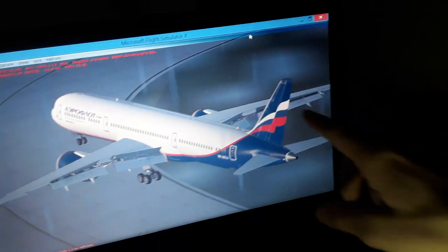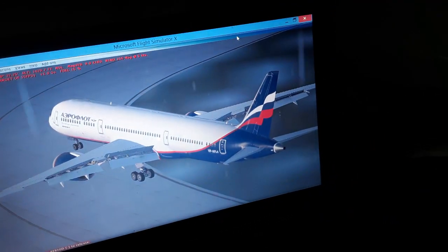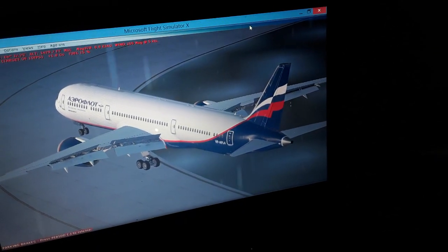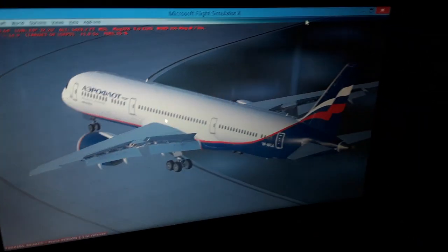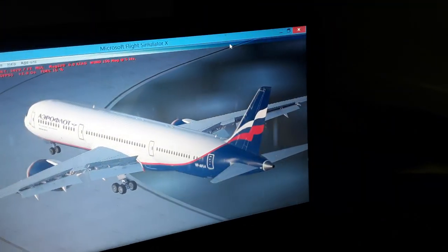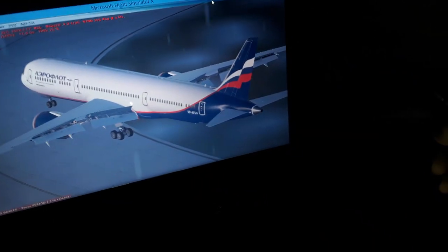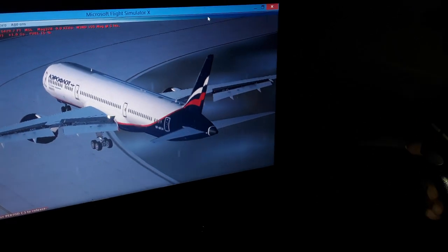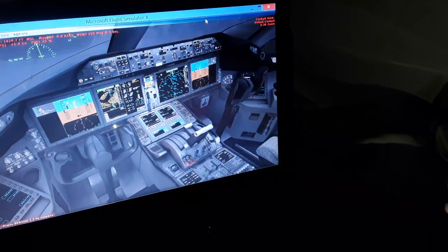Also when we land, the inverse is happening. We have the same thing. We have the rudder first effective from touchdown all the way down to slow down. The nose wheel is coming in automatically from the computers. So this is the theory of the rudder control and the nose wheel together to control on the ground. In the air we have only the rudder to control the left and right turn mainly.